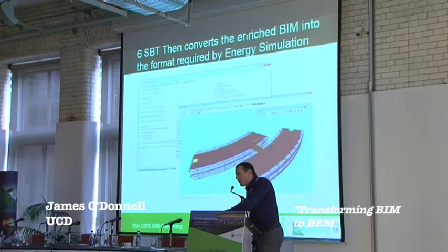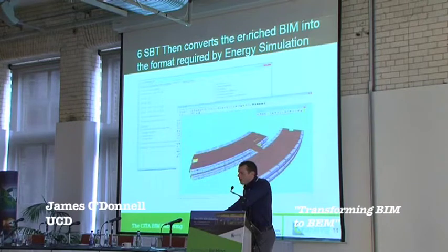Okay, and what we end up with then is the energy simulation representation of the building itself. And we can see here that's in line with an earlier image I showed, but we can notice the heat transfer surfaces on the roof in particular. And when you compare this to a previous image I showed, we had to remove the skylight domes due to the complexity associated with the zoning and the daylighting consequences of that, and we had to develop a workaround there.